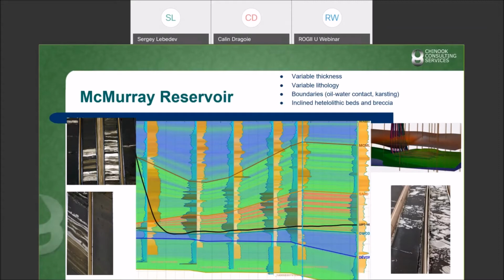A production well that is drilled very close to the bottom of the reservoir, and the steam injection well drilled at a set distance above the producer. Then steam is injected in the upper well that heats up the reservoir, it mobilizes the oil, which flows down gravitationally into the producer well, and that's the SAGD.